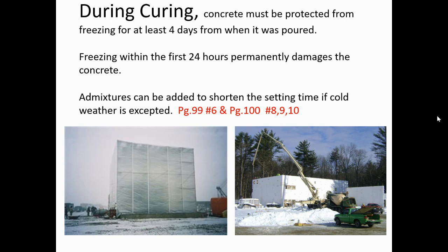If you have any freeze, the concrete's going to be no good. There are admixtures that you can put in to shorten the time, so if you're expecting really cold weather, you could speed up the reaction. Or, like in these pictures, they built big tents around it and they're actually heating that area to keep the concrete warm during the curing process.